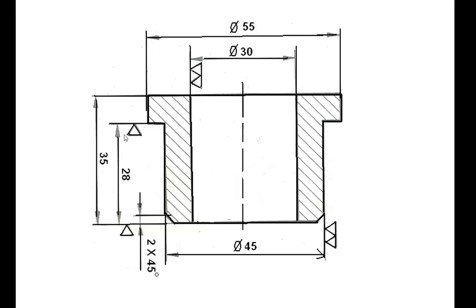It was the quality symbol beforehand in the old format. This means the roughness of a surface shown with 1 triangle is greater than that of a surface shown with 2 triangles. Three triangles means better quality, 2 triangles better quality relative to the first.